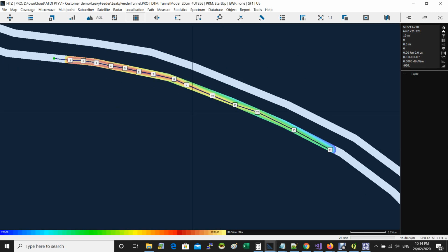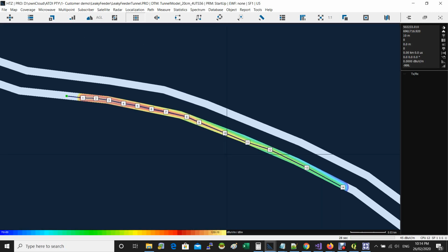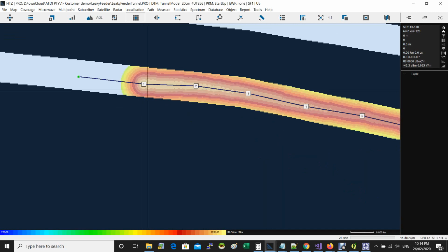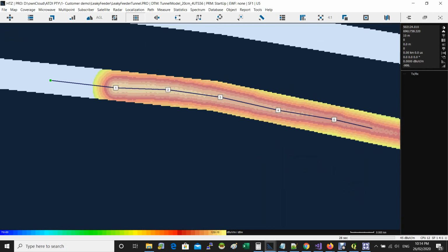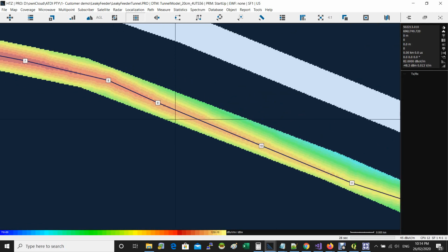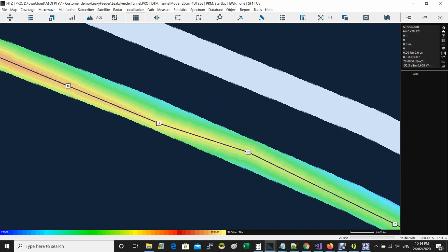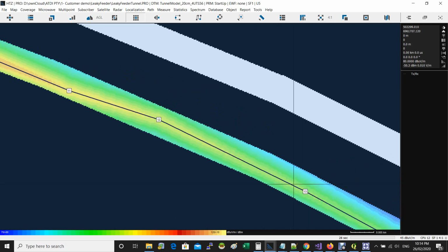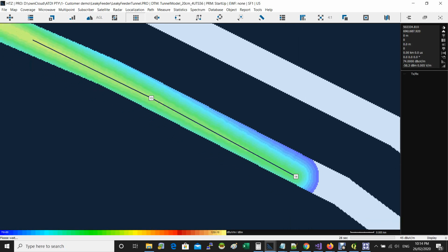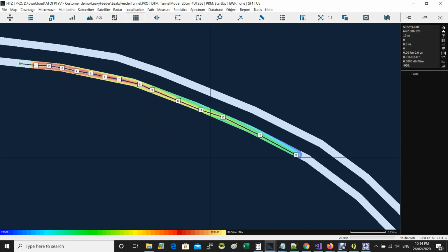All right, here we go. In fact, this is the signal along the journey. Starting very hot, very strong. It starts from here, point number 1. That's where the 2 watt is applied. The signal is degrading as you go further and further down the line. It's degrading in distance along the line and also away from the line, because it's switching down to neg 60 dBm in that case. That's neg 60. Of course, that line can run a little bit further.